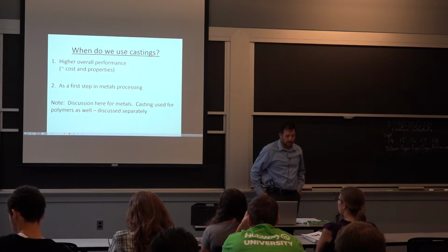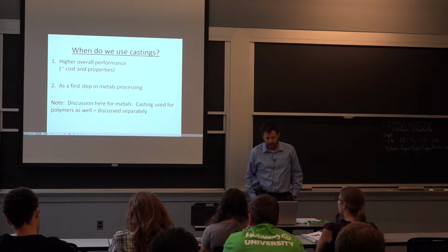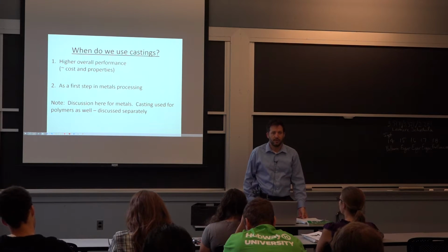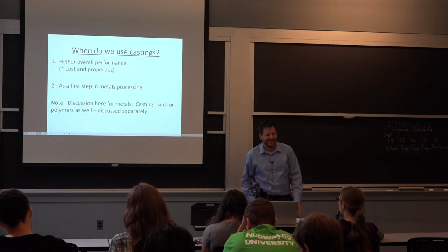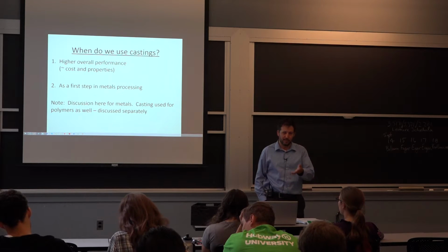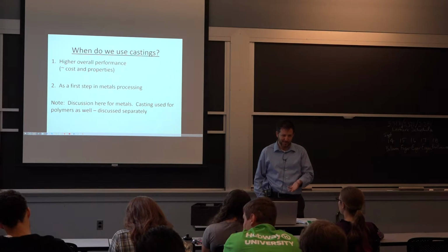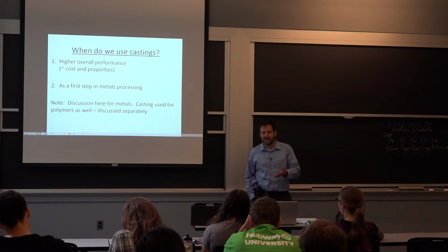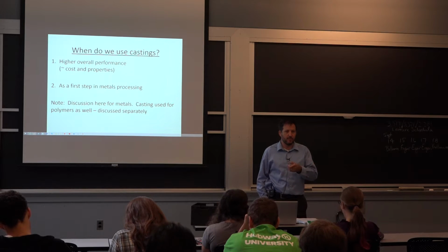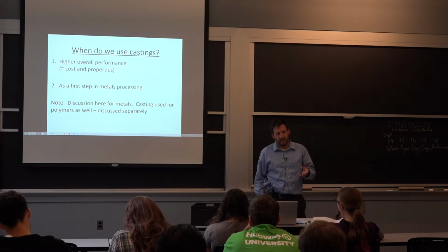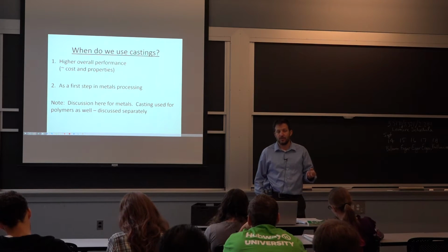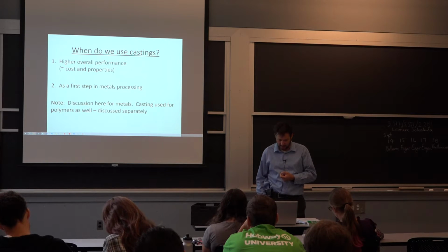So why do we use castings? I think that the general answer is because it's not going to cost as much. There's almost nothing that cannot be machined. Now our additive manufacturing techniques are improving, so there's a lot of things we can build from scratch as well. So cost becomes a main driver. And if you look at that aluminum knuckle I circulated, a lot of the time a combination of not needing the best properties with a complex geometry is a good application for a casting.